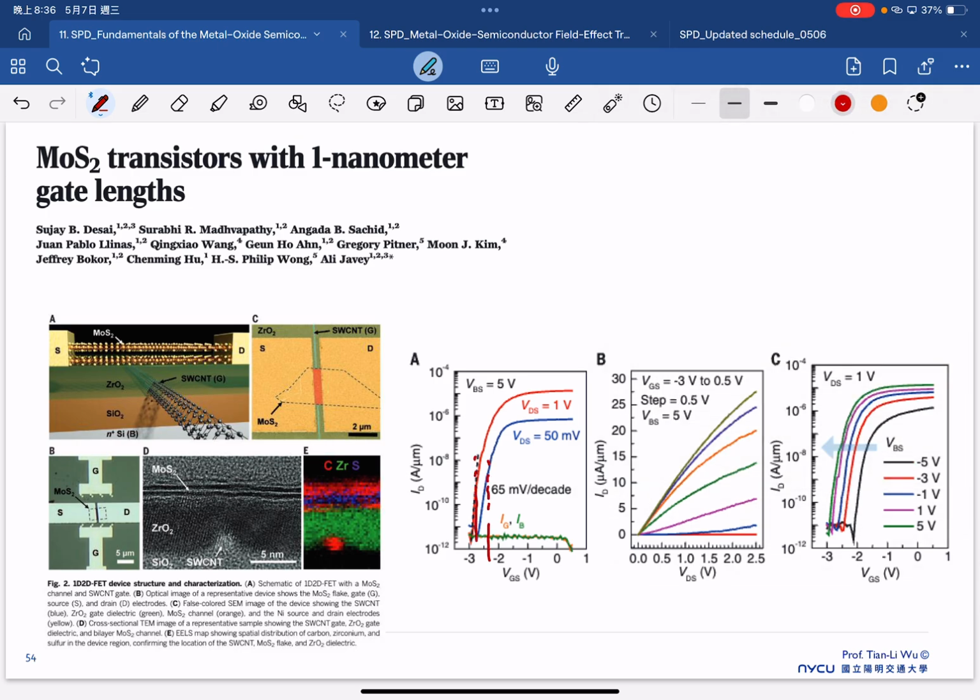So you can see now the threshold voltage is smaller than 0. That means the depletion mode transistor I described is not only one that exists in the textbook, but also one that in reality people occasionally have. In a real situation, we always want VTH larger than 0 volt.